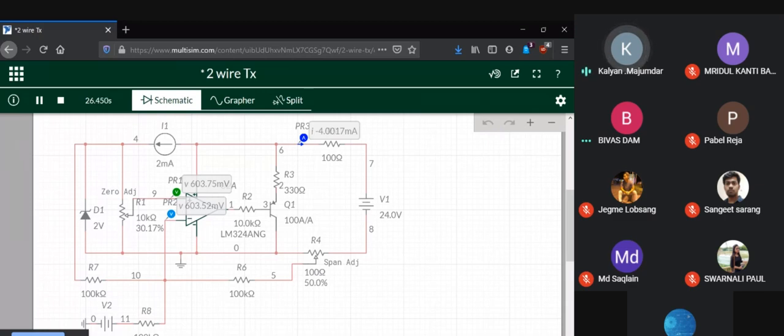That is important, because otherwise the input doesn't change but the loop current changes, and then the value the indicator displays changes, though what you are measuring did not change. So you have a measurement error. The indicated value should always be identical to the actual input value, so you should ensure that the loop current is independent of loop resistance and supply voltage.